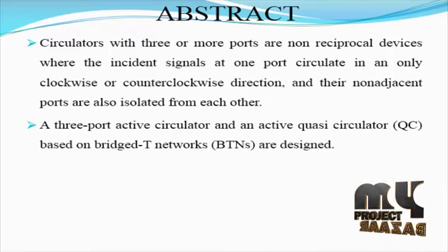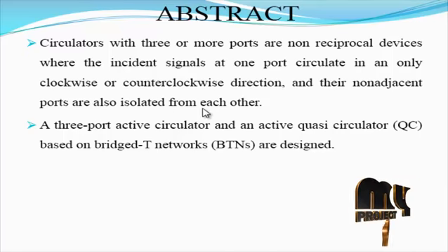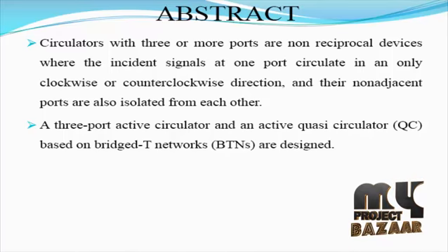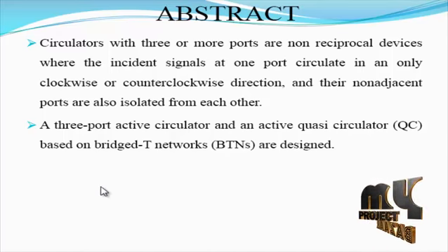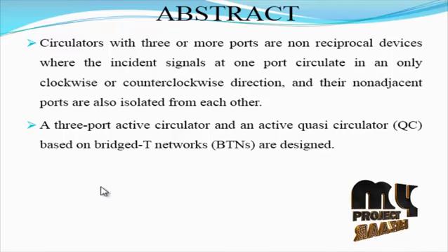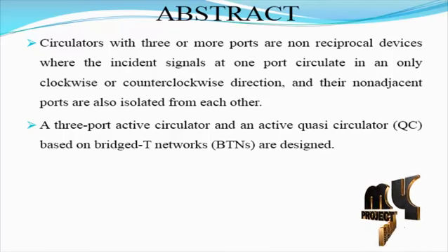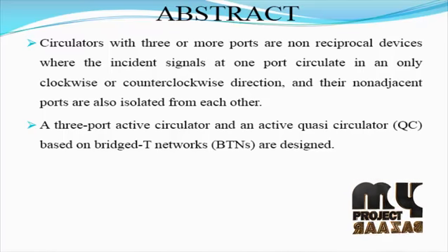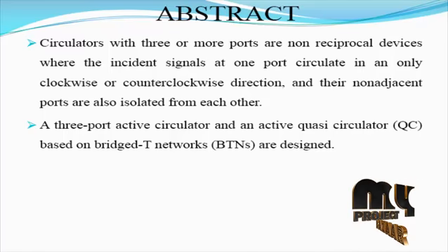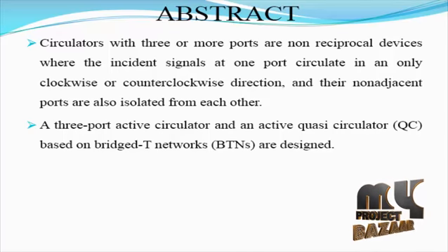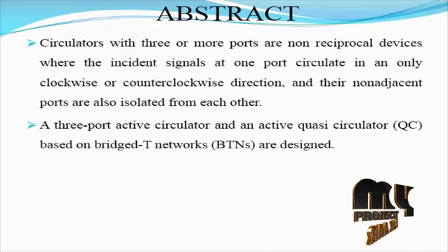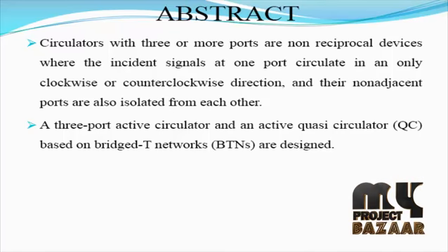In our product, we have designed circulators and quasi-circulators with Bridge-T networks. To eliminate the use of ferrites, the use of non-reciprocal characteristics of transistors for an active circulator was first reported. The 3-port circulator with 3 MHz operation frequency used 3 transistors in a ring-type configuration.